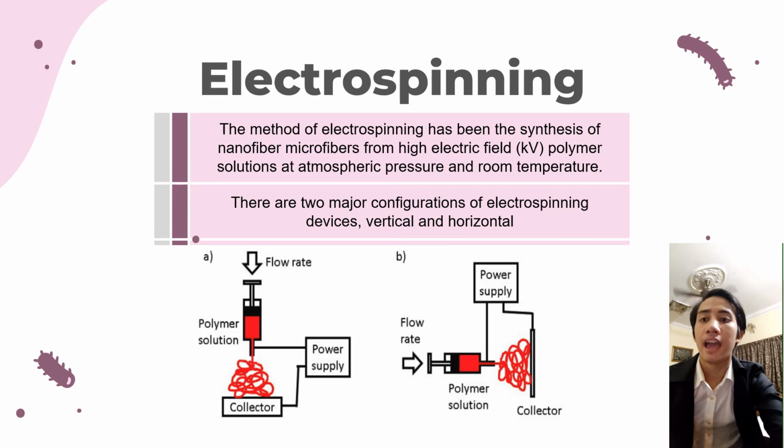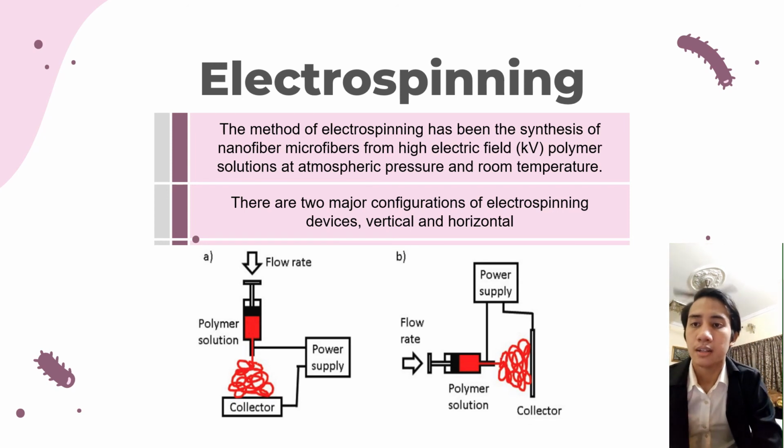Electrospinning devices have two main setups, vertical and horizontal. Power supply, high voltage, spinneret and collector electrode are considered the main components of the electrospinning device. High voltage generates electric charge on the polymer solution and this charge accumulates on its surface. These charges repel each other such that at a critical electric field they are able to overcome the solution surface tension and form a Taylor cone.